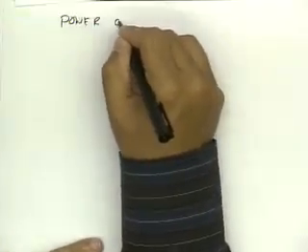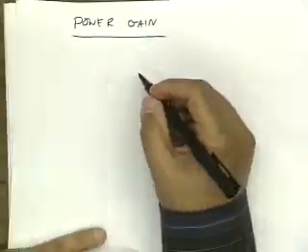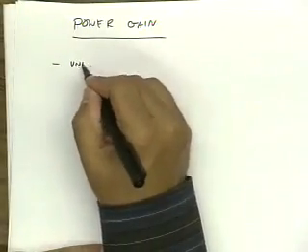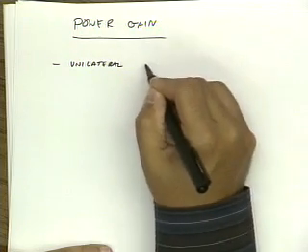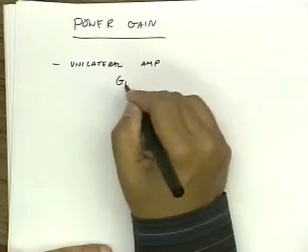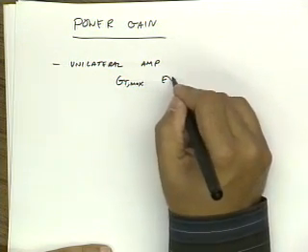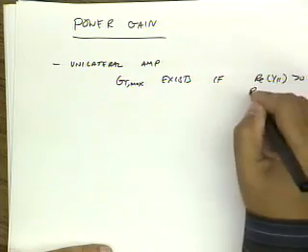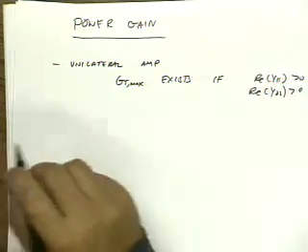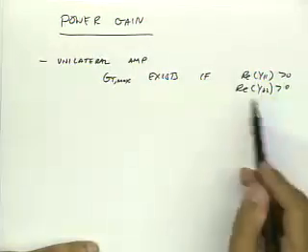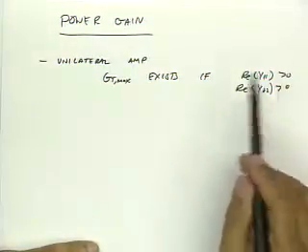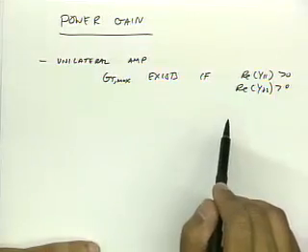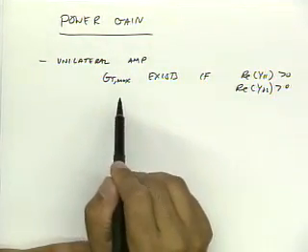Okay, so let me come back to this equation, this question of power gain in general. So what we found is that for a unilateral case, GT max exists if simply real part of y11 is bigger than 0 and real part of y22 is greater than 0. And if it's a physical transistor model, usually this is true. So you almost don't need to check this condition, but usually it's already satisfied. So for a unilateral amplifier, we can always find the maximum gain.